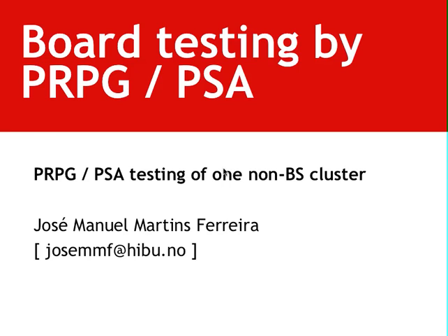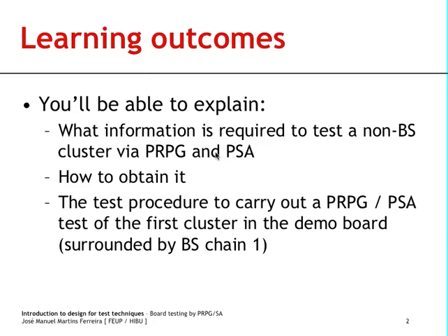Second and last video in this playlist addresses the actual testing of one of the non-boundary scan clusters using pseudo-random pattern generation and parallel signature analysis techniques. After watching this presentation, you will be able to explain what is the information required to carry out this type of test in a board, and also how you can obtain it.